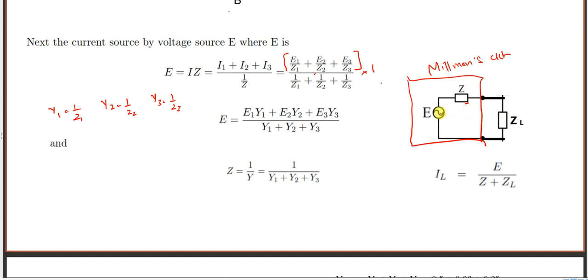I am telling once again, if it is a resistance network, we are going to get effective E and equivalent R here, and this will be RL. And you can find the current through this. Current through this one is given by voltage divided by the sum of resistance or impedance. Here, this is a series circuit. Z and ZL are in series, and in the entire circuit, the voltage is E. So E divided by Z plus ZL.